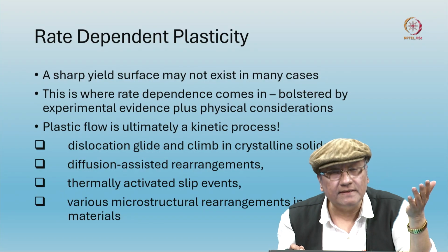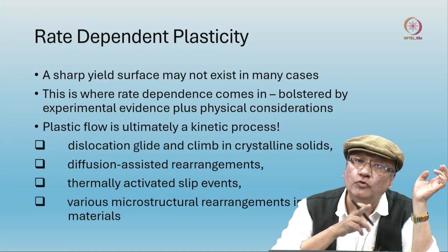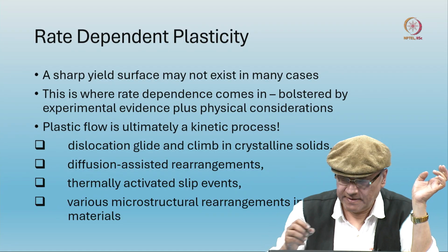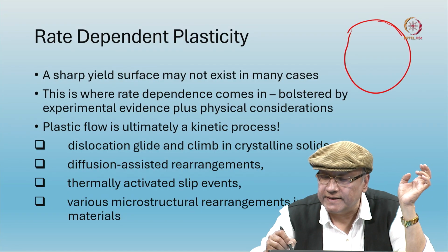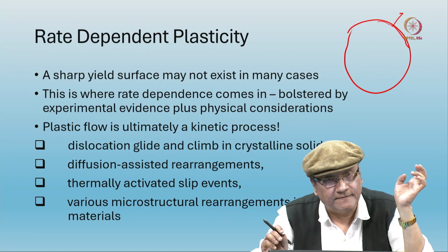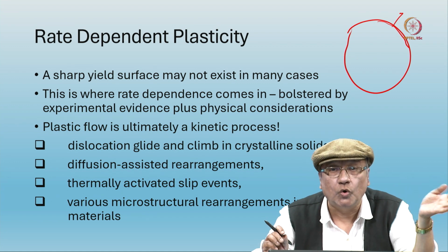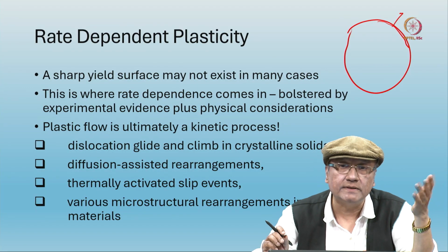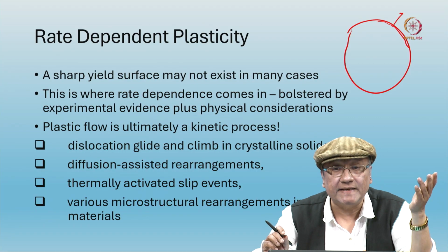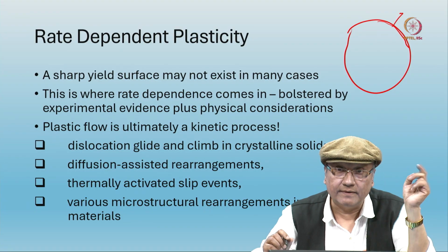It may admit a so-called yield surface, but stress can move beyond it. So far, stress always remained on the yield surface, and the flow direction was the normal to that surface, the normality rule, or in case of non-smoothness, the normal cone. All the elements within that normal cone gave us all the possible directions of plastic flow. But no more.